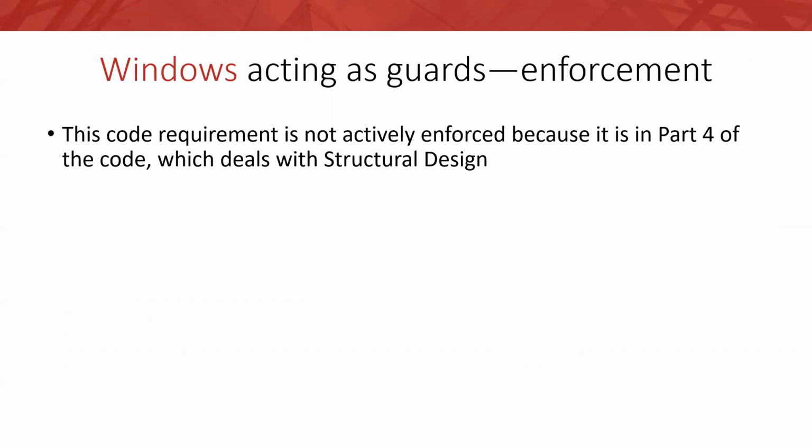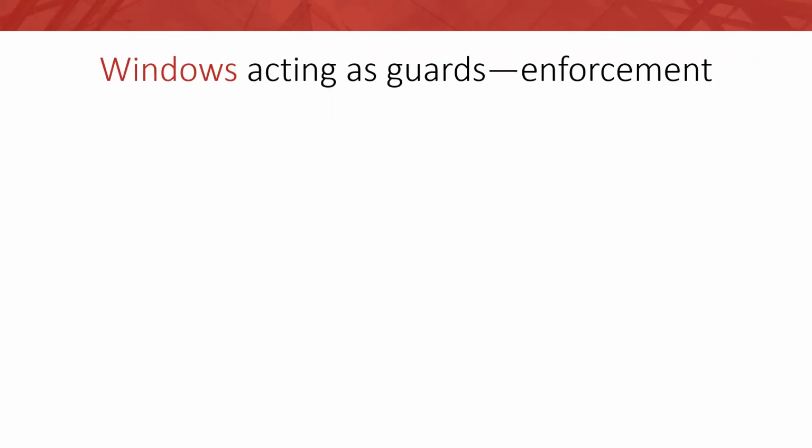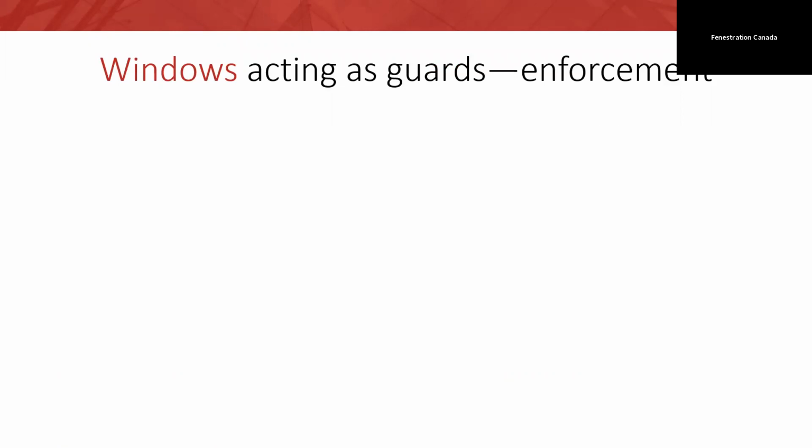Just a second, guys. I have a question here from John. John's asking, are the load on guard requirements the same for residential suites, and are they different from a fixed window versus an operable window? So what we are getting is zero enforcement on Part 9 buildings, but residential suites within non-Part 9 buildings, yes, absolutely, it applies. And we've got some slides that address the latter part of the question.